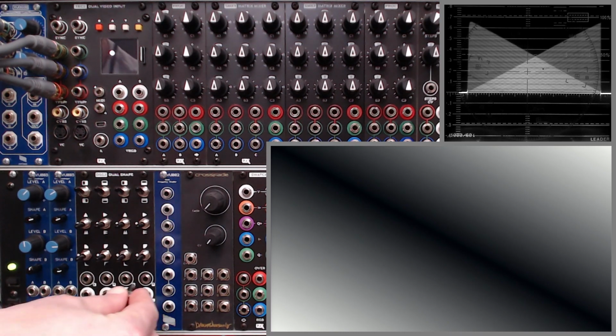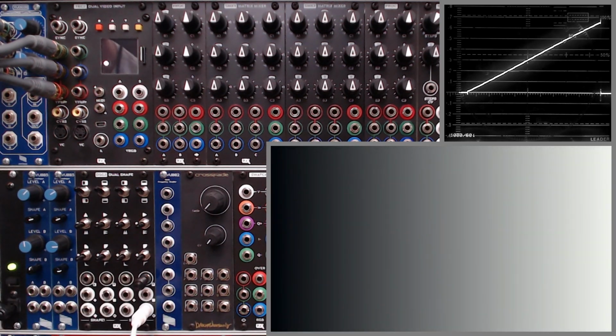If I put a dummy plug or a 0 voltage source into that vertical input, we're breaking the normal to the ramp, but we're not supplying any other signal. And so we're basically just getting black on that vertical channel. So now what we're seeing is the absolute value of the difference between the horizontal ramp and black. And predictably, horizontal ramp minus black equals horizontal ramp.